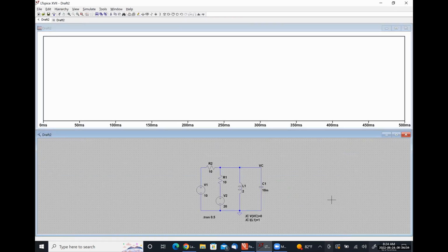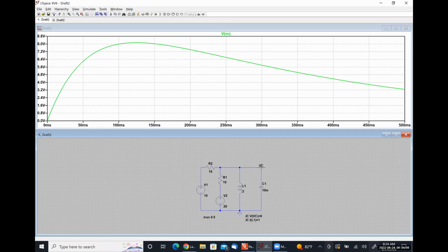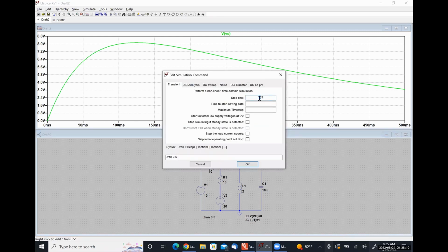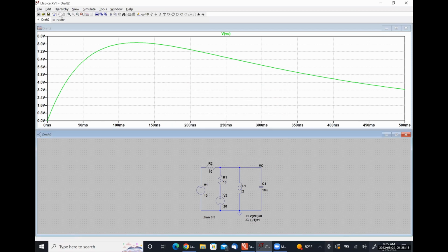And it's going to start off with nothing, okay? So the first thing I'm going to do here is click on my capacitor voltage. This is not the signal that we were explicitly looking for, but we did do some work for it, so I want to see whether I did that right. So I click my voltage probe on the positive polarity terminal, and I get this waveform. I can see right off the bat that it doesn't settle to 0 in this half of a second. So I'm going to change my transient analysis, and I'm going to look at it for 1.5 seconds just to see how this goes.